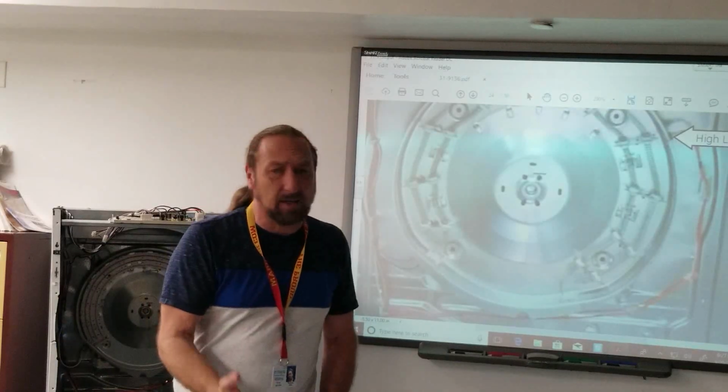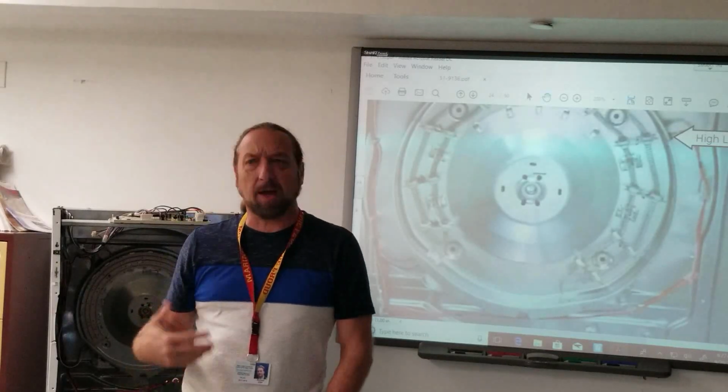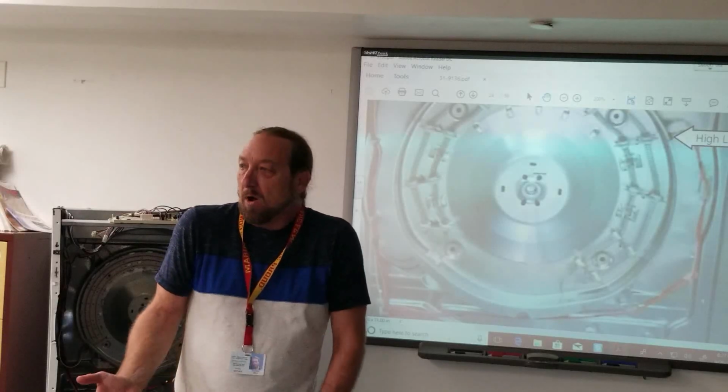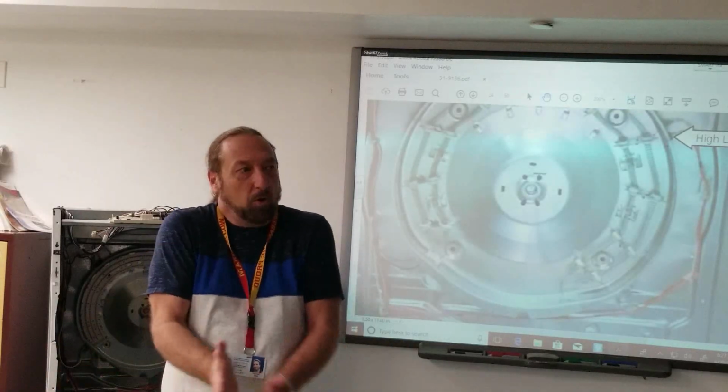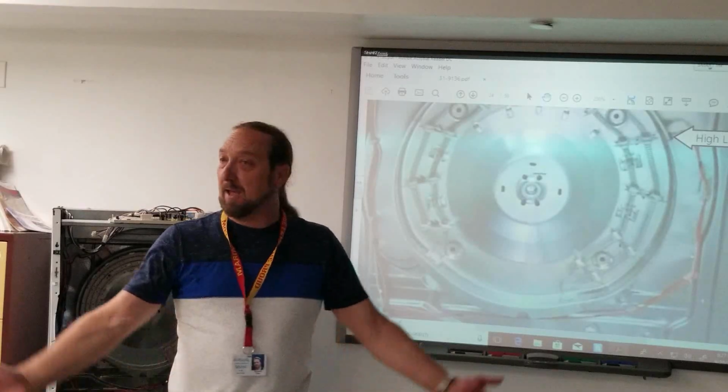Am I going to check to see if I have 240 volts? Am I going to see if it gets hot? Yep. I mean, we're first going to turn it on and see what it does before we start checking anything. But how often have you guys worked on dryers and saw the hose crushed in the back or the machine not installed right? Every single day.